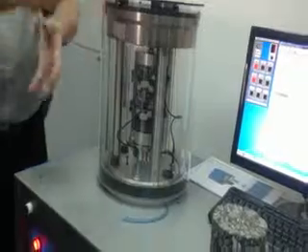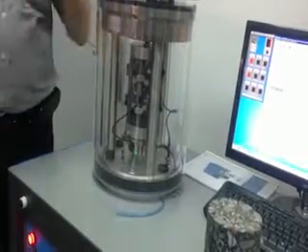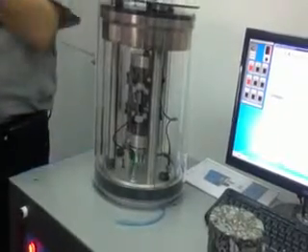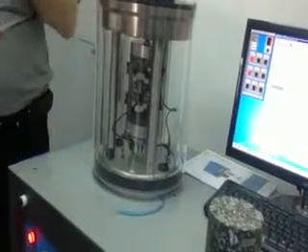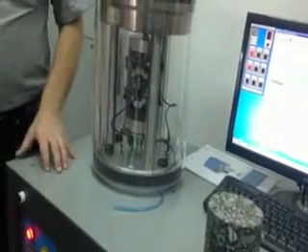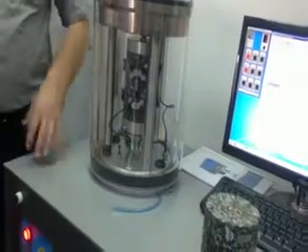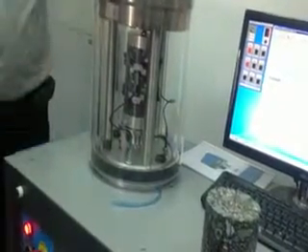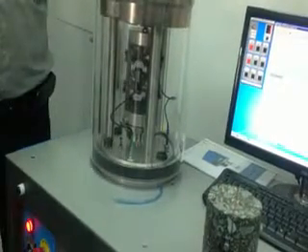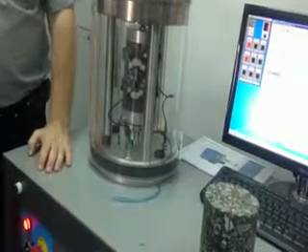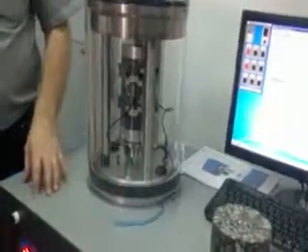So if you had 5 or 6 samples, you do all of them at one temperature condition, then put them back into the oven. That means the same casting sample, as before. For example, we will cut 5 or 6 cores and test different samples at different temperatures. You go from the low temperature to the high temperature, always. If you start at the high temperature and it's a very soft material, you might have problems. That means one sample cannot go for different temperatures.